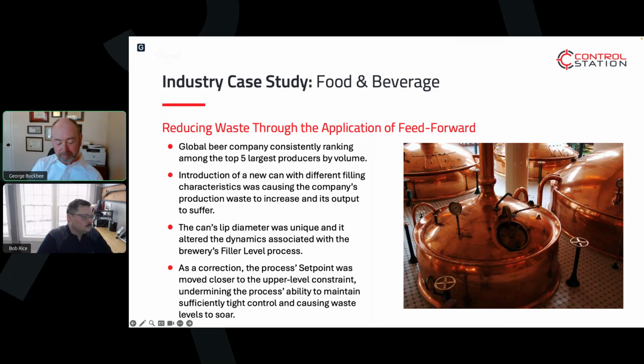If you underfill it, then you have to pull those bottles aside, because obviously you can't sell them at underweight or under volume limits. So is there enough here to be worried about, to think about doing something different like feed forward control? Absolutely yes, because there's a lot of giveaway and a lot of culling of these underfilled bottles. So there's a rework cycle involved. It's just a painful, costly part of the process.